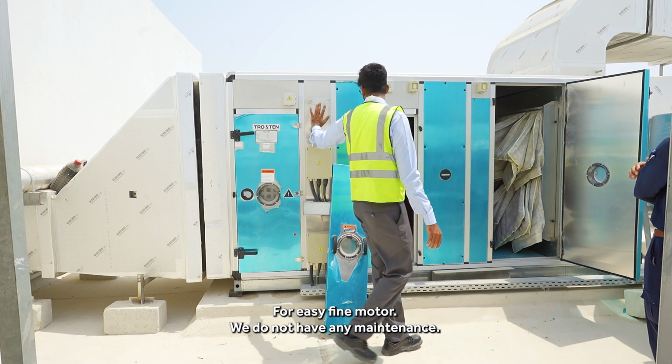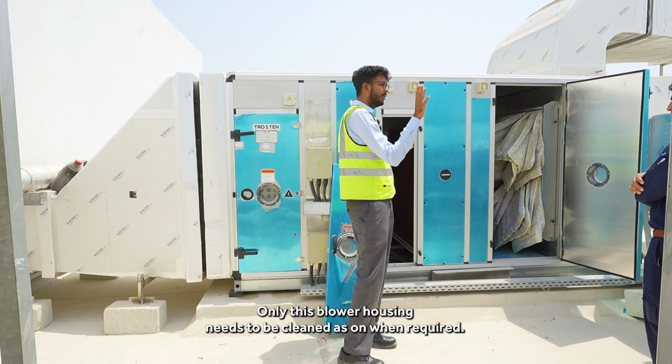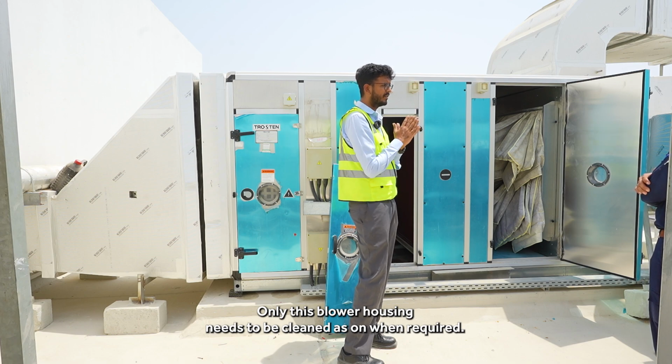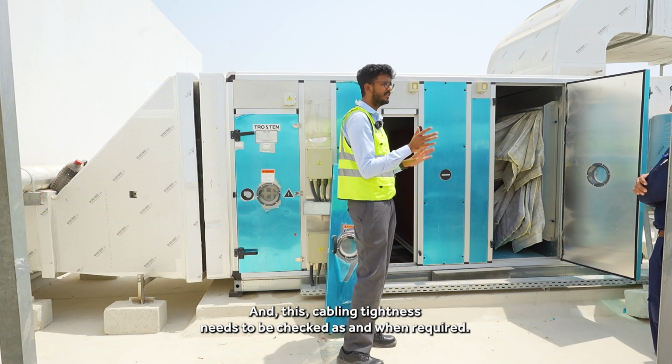For the EC fan motor, we don't have any maintenance. No maintenance required. Only this blower housing needs to be cleaned as and when required, and the cabling tightness needs to be checked as and when required.